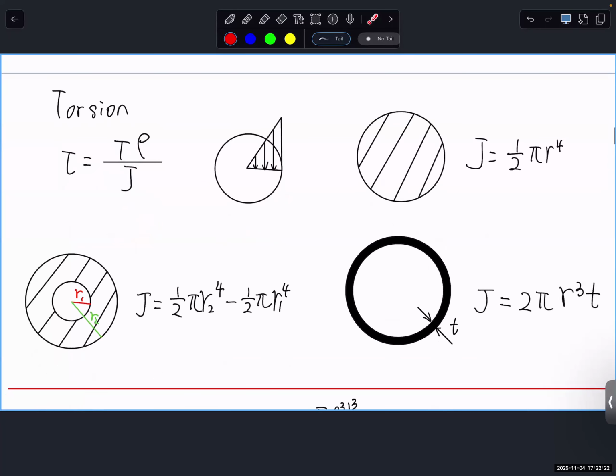And so now it makes sense when you see a lot of structures in real life. Why do they make the thin wall? Because only the outer surface carries the maximum stress. And if you want to have a structure that survives that torque and does not fail while maintaining minimum weight, which is very important, I don't know about orthodontics, but very, very important for aerospace, because everything you want to fly, you want to have minimum weight.